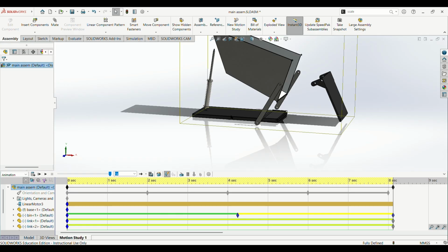First, we have the truck chassis. The truck chassis acts as the ground on which the whole model is based. Second, we have the dumper bin. The dumper bin will move its angle based on the input given by the third part, that's the truck actuator. Now the truck actuator will move up and down, and this will cause the third link to move. And as a result, we have the fourth linkage, that is the truck door, that moves. And we have to maximize the angle of this truck door.